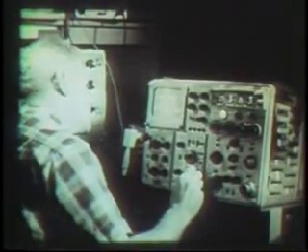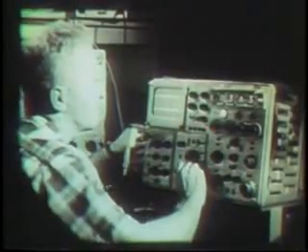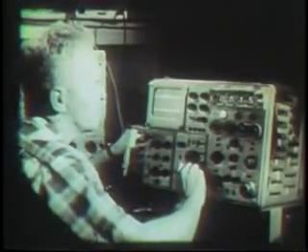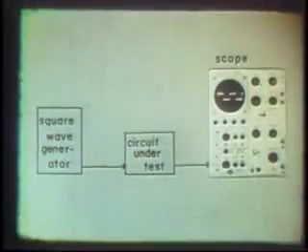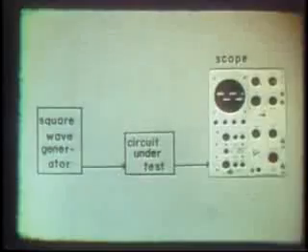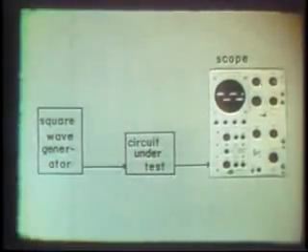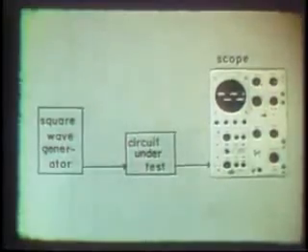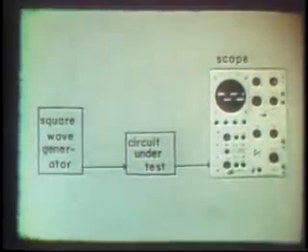The usefulness of the square wave in testing electronic apparatus becomes quite apparent now. For a square wave to pass through an electronic circuit without any change or distortion, that circuit must be capable of passing a wide range of frequencies without altering their relative amplitudes or altering their phase relationships. If the circuit is not capable of this, the square wave will appear distorted at the output.